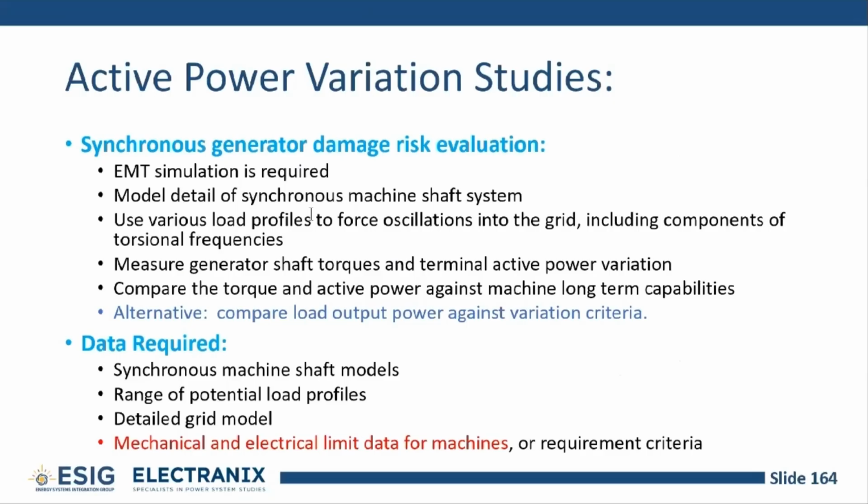Now, for this application, we're really not interested in that part of the SN curve. We're interested in the bottom part, or extrapolating that out forever and finding an endurance curve. Those curves, I've never actually seen one. I know they exist, but when we push vendors, and even with a significant amount of leverage from generator owners, I know there are generator owners in the room who have leaned on their OEMs for this kind of data to try and help them design a plant. It seems they're not giving it up. We're not entirely sure why, and I'll keep my opinions to myself. It seems to be hard to get.